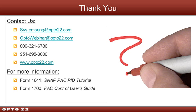Great. Okay, thanks, Ben, and thank all of you for attending. Oh, I've got one more question, and then we're going to wrap this up. Victor is asking, the recommendation you make about the type of PID you use is based on what, or the default Opto? I think what he's asking about is the choice of the algorithm, and we've been recommending the velocity type B algorithm. Correct. Yes, so that a set point change is picked up by the algorithm. The velocity type C doesn't see that set point change, and so it's not going to respond as well to set point changes. So yeah, and the default is the new type, that's the type B.